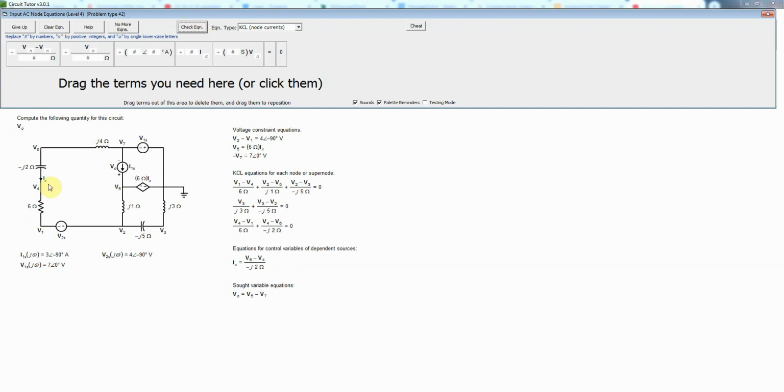So that is correct. Now we'll look at node 5 and say, okay, node 5 is actually connected to a voltage source. Doesn't matter whether it's independent or dependent, it's still a voltage source. It still has those little plus and minus signs in there that tell us it's a voltage source. And it is connected to the reference node. That means it's part of what we might call the reference supernode. So we do not need to write a KCL equation for node 5, and we will not attempt to do so because you really can't.